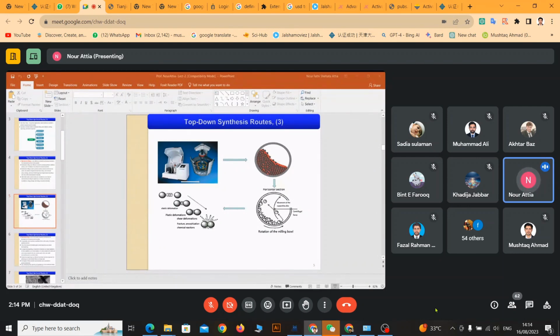There are many materials you can prepare. I told you, you can prepare animal bone, which is sometimes hydroxyapatite that you want to use for something. So you can just collect the animal bone, break it down, then put it in the ball mill, and then you will get nano. It's easier. But it's important for you to know what you're doing and to put in some soft material to avoid aggregation again.